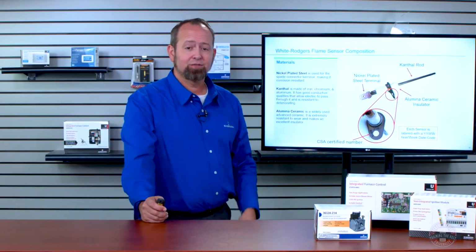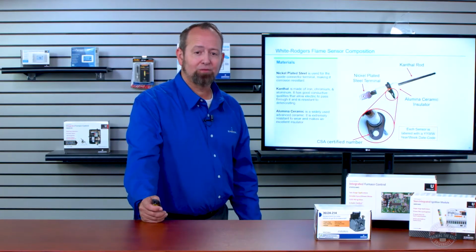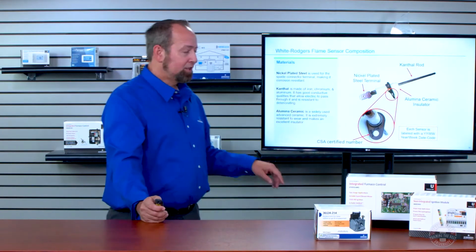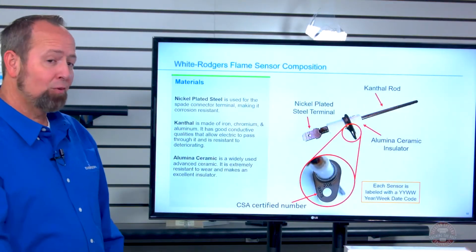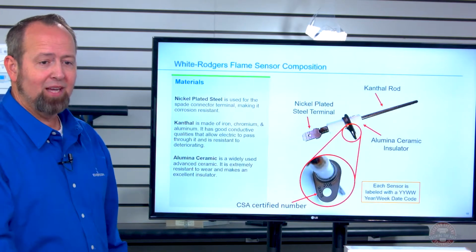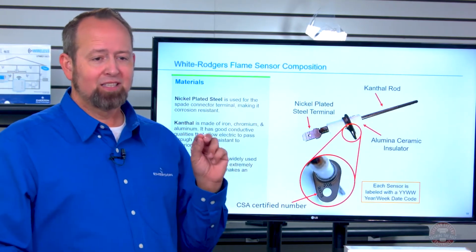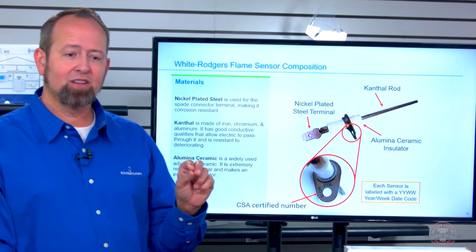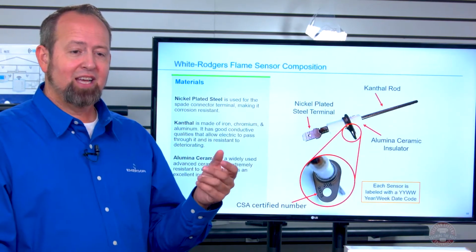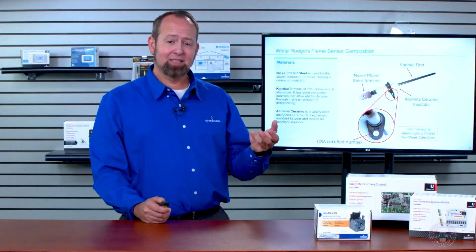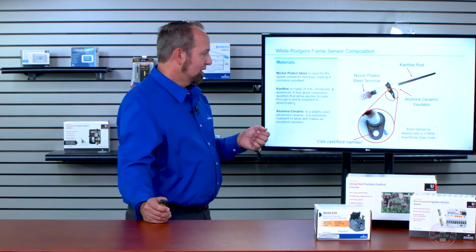The actual terminal is a steel nickel-plated terminal, and that nickel plating helps keep solid contact on the wire so that it doesn't corrode and weaken the flame sense signal going back to the control board.